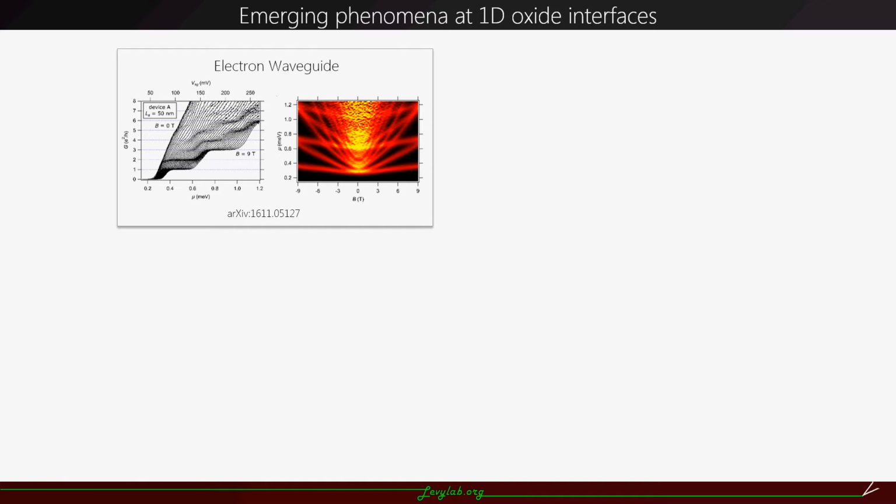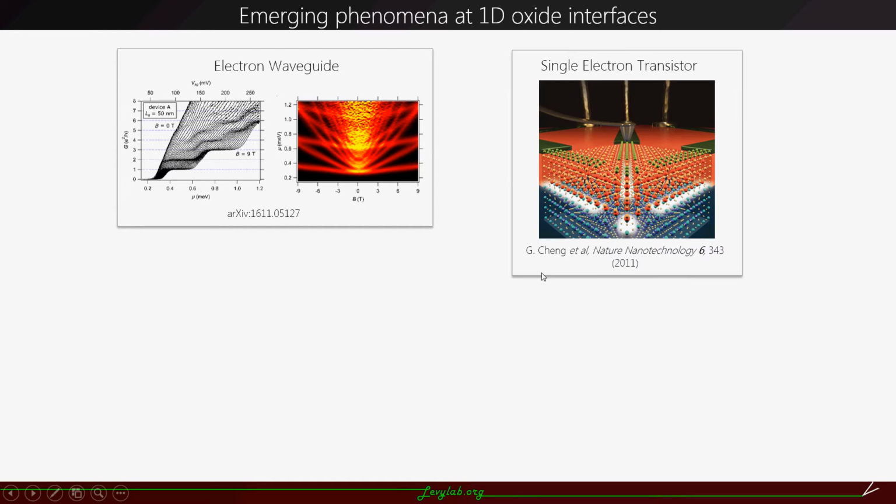Nanowires are important for studying electronic correlations. By placing two quantum point contacts in the nanowire, in our lab we observe quantized transport, which confirms ballistic transport and the high quality of the nanowire created in our system. We are able to fabricate nanowire-based single electron transistor.